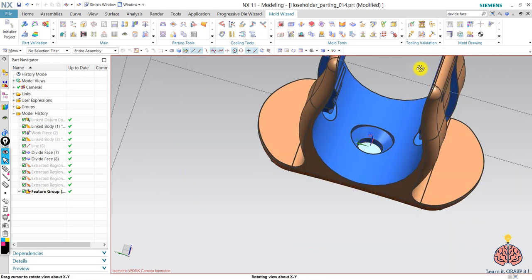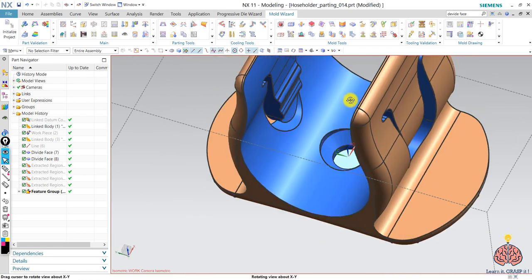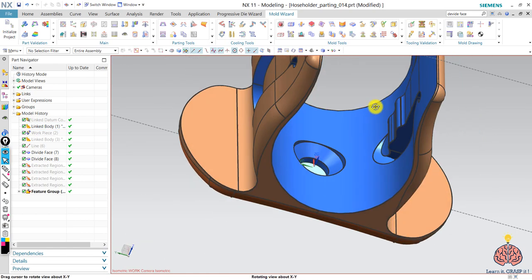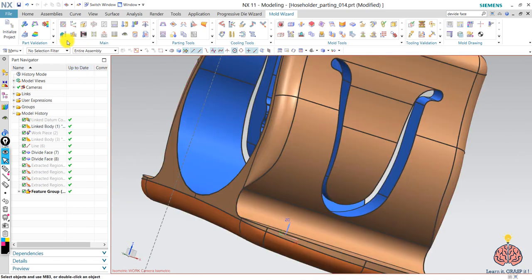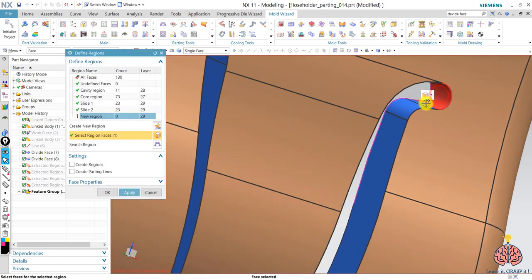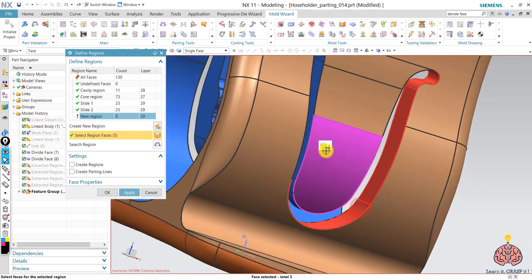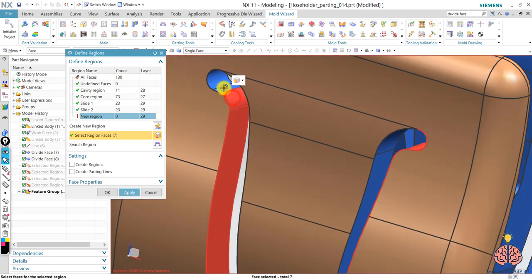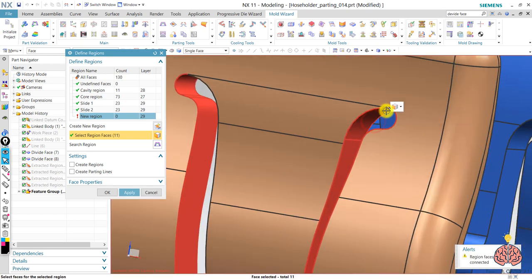We also have the slide, like as we said before, that the core will have all of these surfaces, right? And we already patched this, but we need to patch these openings. Before we do this, we forgot something: these faces belong to the slide, because if you could imagine it, you will find out that this belongs to the slide, not to the core.